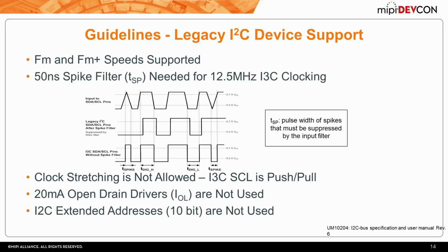In order to gain the efficiencies, speeds and performance, we really favor in I3C a push-pull clock. We very much encourage that because, as mentioned, clock stretching relies on open drain on the clock. We want really nice, fast, crisp edges on our clocks.